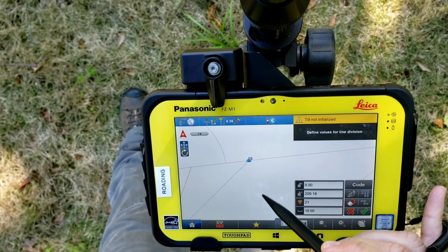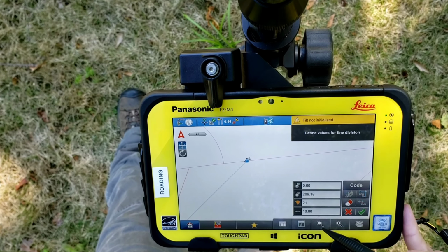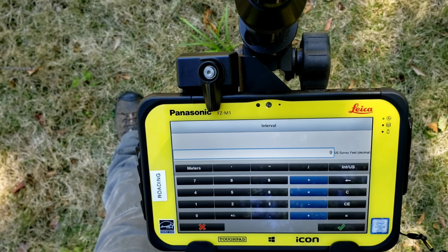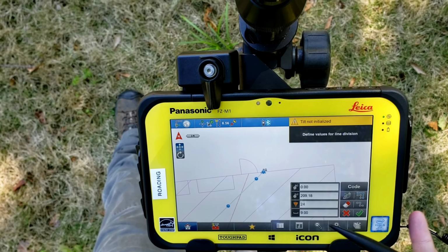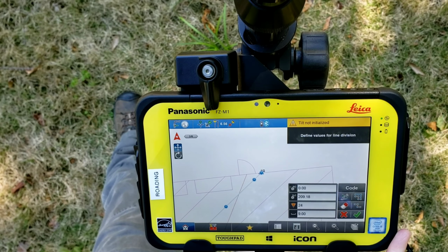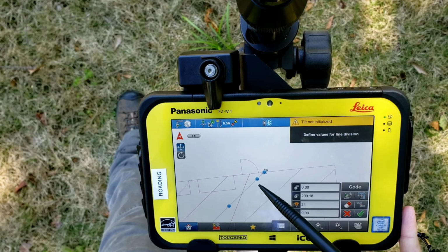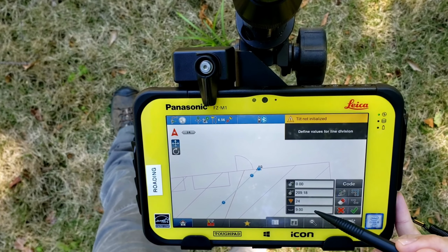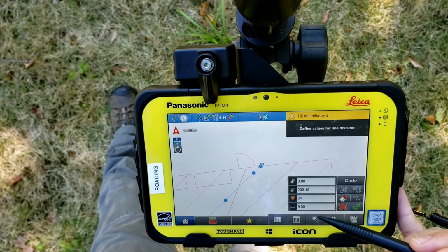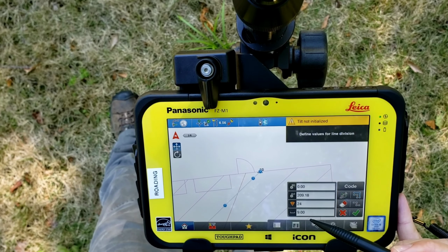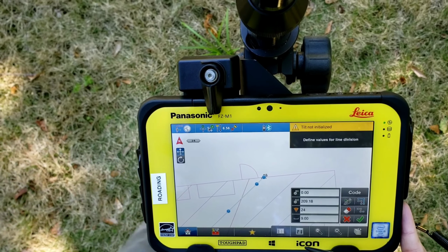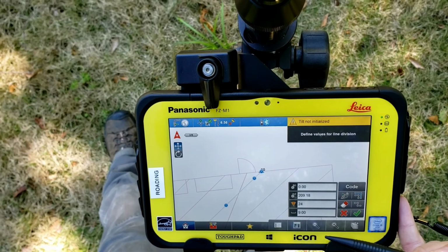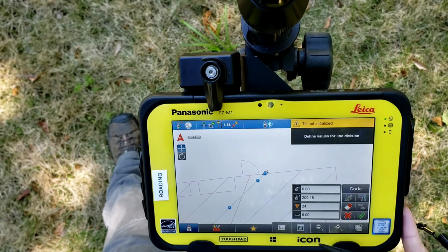If you see a couple that are close there, that's just because, let's do 9 feet. There you go. If you do 9 feet, it'll start from the beginning, run them up at intervals of 9 feet, and then your last one's going to be a little bit short to finish it off. So that's a handy tool. You can use that with lines and with arcs. Definitely handy for arcs because they're a little more challenging to get your stationing.